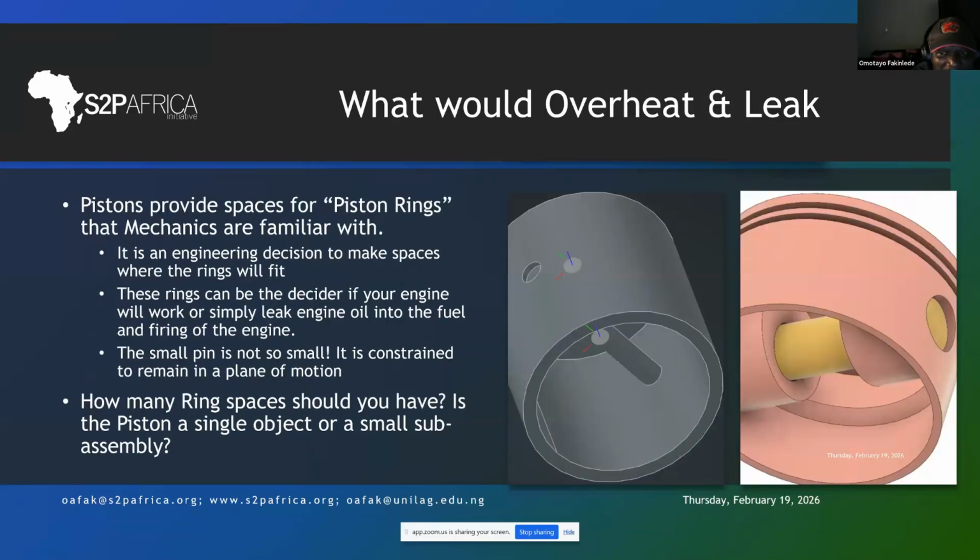Just like we have said about the connecting rod, we can also look at the piston. You can see that there are two types of piston. This is the piston we have used in our example last time. And this is the piston I am expecting you to be able to design. You will see that there are pins in both pistons. The pin here is definitely stronger. Not only so, it is more firmly held. The position of the piston holding the pin is much stronger.